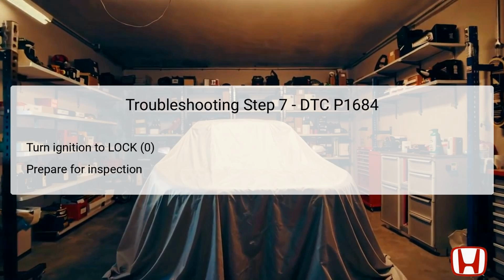In Step 8, the intake air duct must be disconnected from the throttle body to allow for direct access to the throttle mechanism. Care should be taken to avoid damaging any associated components during this disconnection. With the intake air duct removed, the technician gains clear visibility of the throttle cavity, allowing for more accurate diagnostics and potential repairs.